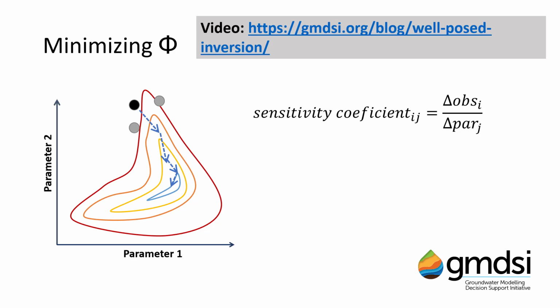Again, as mentioned earlier, one approach to minimizing this cost is to reduce the number of adjustable parameters using parameterization devices such as pilot points. Thus, instead of attempting to estimate the values for all model cells, we can reduce them to a manageable number of pilot points, while still retaining the ability to express heterogeneity. Of course, the ease of access nowadays to parallelized computing, whether through local networks or in a cloud, allows many model runs to be carried out in parallel, speeding up this process significantly.